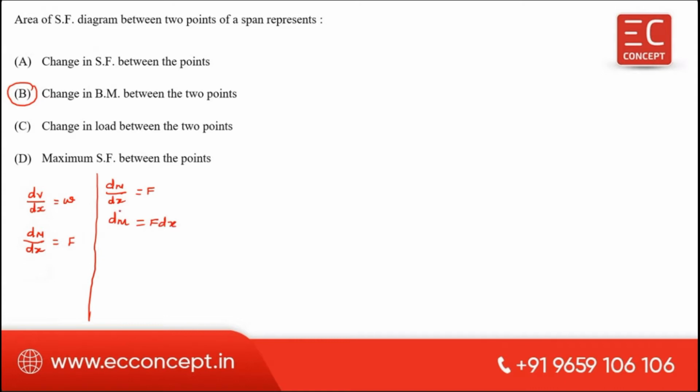If you integrate this, then you will get a moment. This is the change in moment, right? dM is what? Change in moment. So change in moment is equal to what? Area of shear force diagram. That is, change in moment is equal to the shear force diagram area.